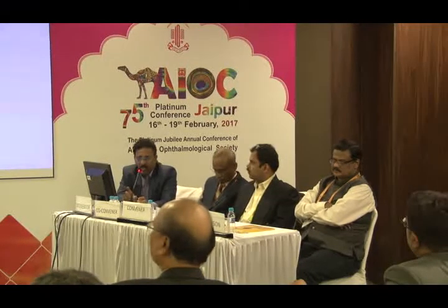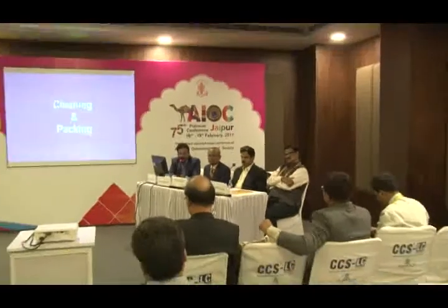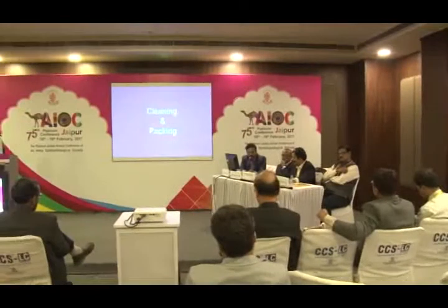There was a question about commissioning a new theatre. Fogging is allowed for the first 3 times, but once you install HEPA filter, please do not use fogging or fumigation, because these aerosols and particulate matter of the formalin or any other chemical used go and block the HEPA filters. So the efficiency comes down and the filter may not work to its validated arrangement. So while commencing, the fogging is also done through AHU without HEPA filter? Yes. So HEPA filter should be the last to go into a new theatre.